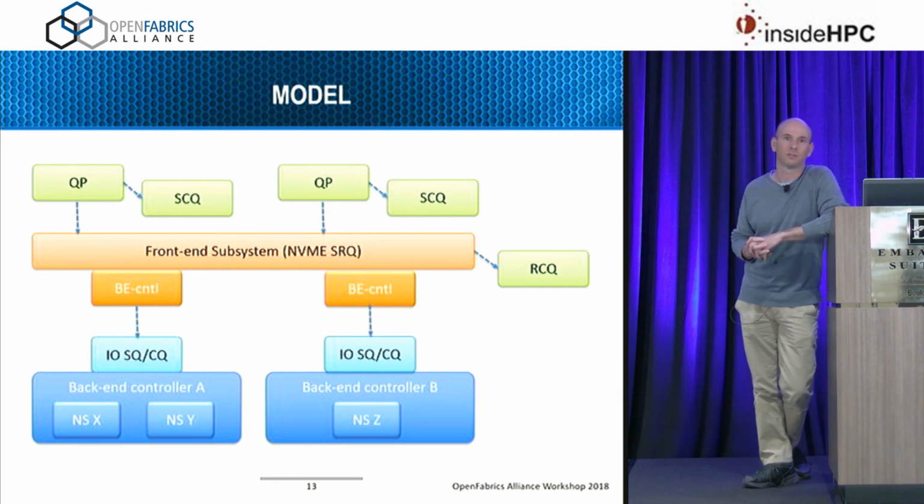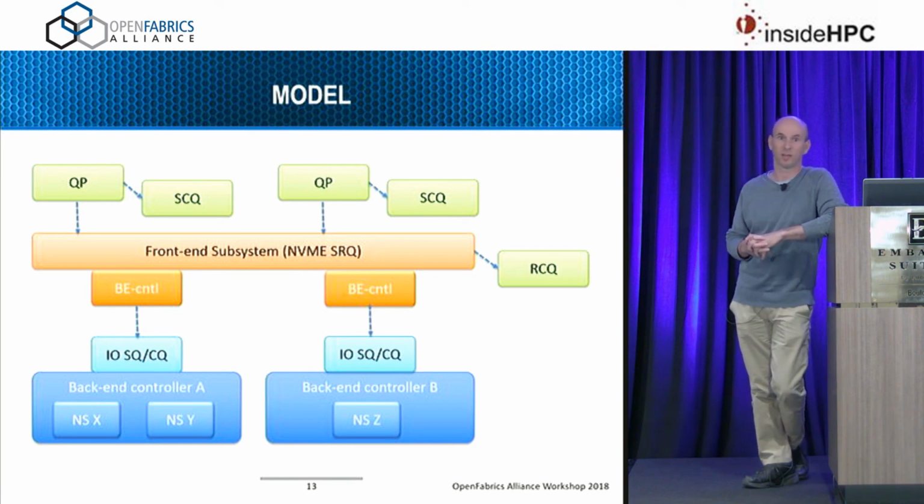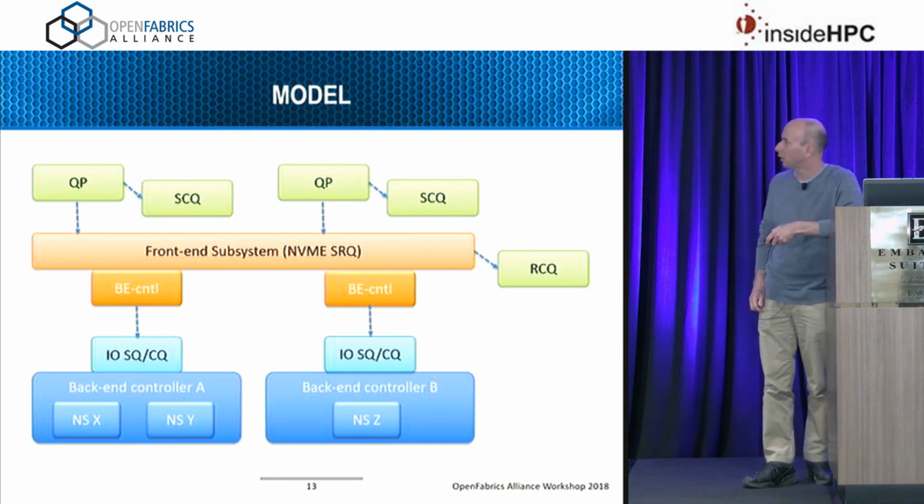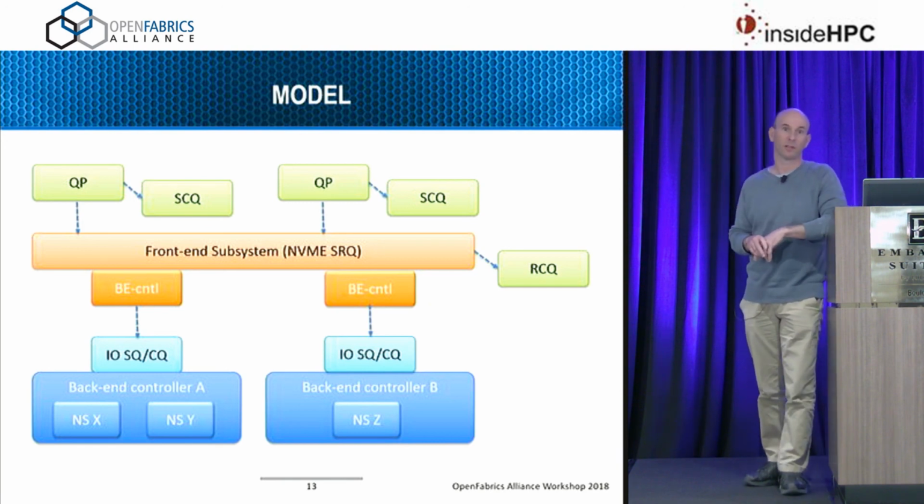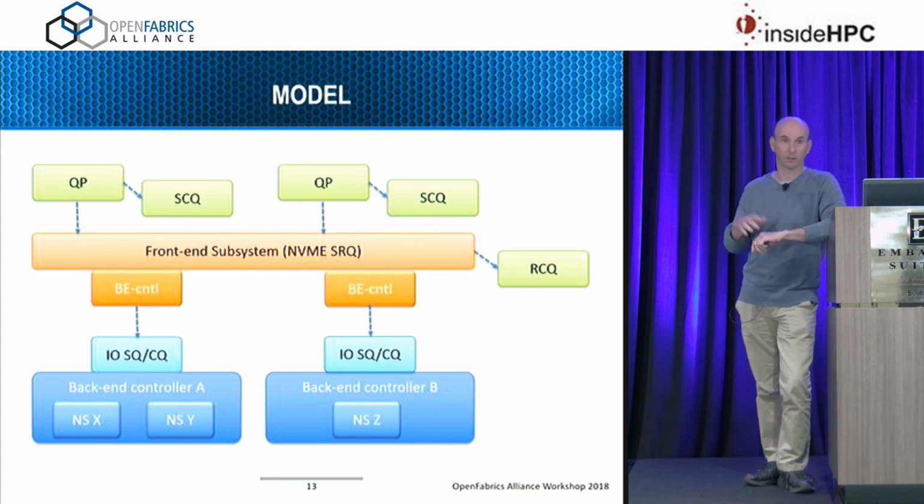And then the second question is, I noticed that you have your NVMe completion queues in host memory. So they're mapped up into host memory, right? How does the offload know when a completion was written? Okay, so first of all, I don't think that the NVMe device cares where it's mapped. It just knows that it doesn't reside on the NVMe unless you mapped it to the controller buffer of that NVMe. The way you know it is that we tell the offload these details. This is the purpose of this backend controller object. Basically, we specify the physical memory address that holds the completion queue. So when you have that parity bit where you detect NVMe completions, the hardware actually polls that bit and detects the completion just as software would.